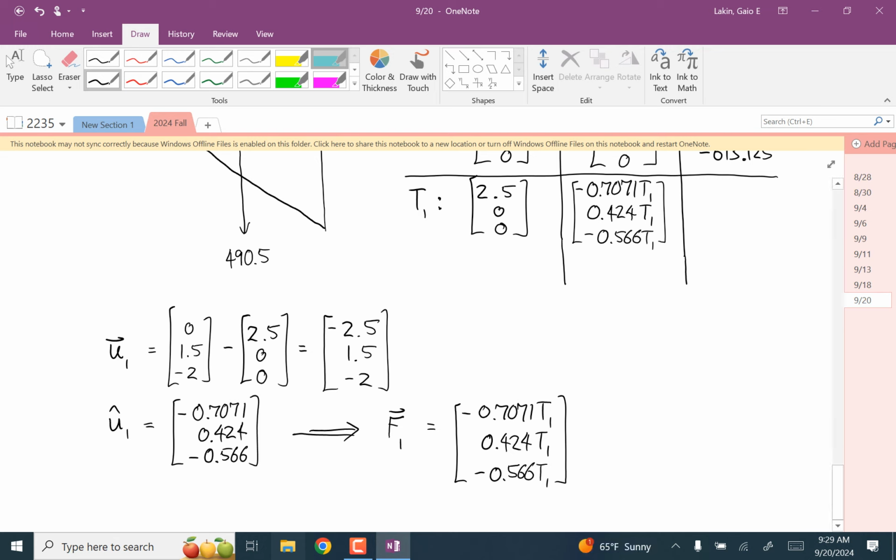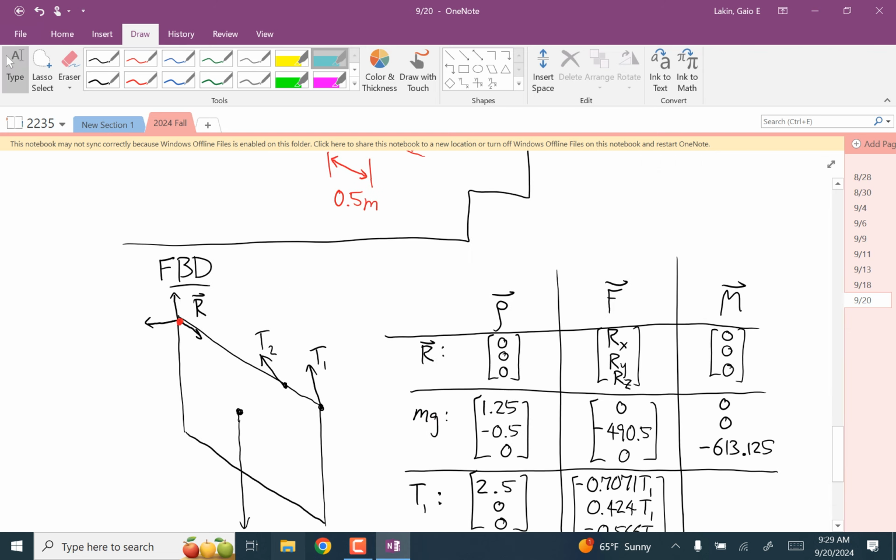I've been checking my work by keeping my sine and cosine in there for the 2D stuff. Is there a way to do that with 3D? Not really. I mean, yes, there is, but this is the way you want to do it in 3D, because you have to combine rotations out of plane. You could do it with rotation matrices, but you don't want to do that. So in 3D, you always want to find coordinates, subtract the coordinates, and then take the unit vector. Cosine and sine only work in 2D in any practical sense.